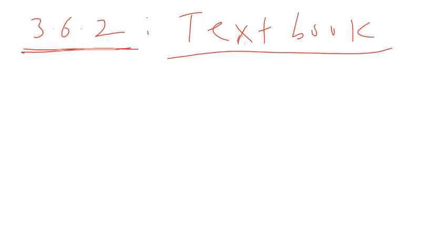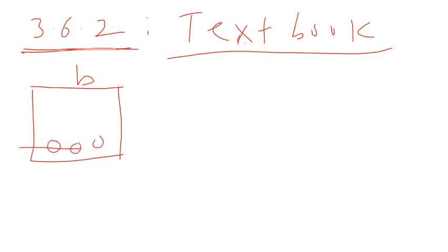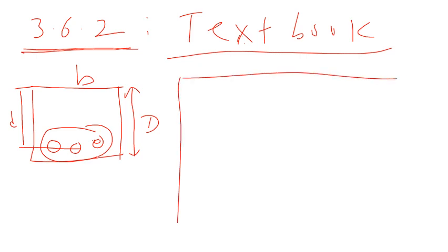So we have to find out the smallest concrete section. If you notice, B is already given, right? So our job is to find this small d, and we have to find out this capital D, and also we need the area of the steel, that is Ast, right? So these are the things we have to determine to design the smallest concrete section. So let's start with this problem.